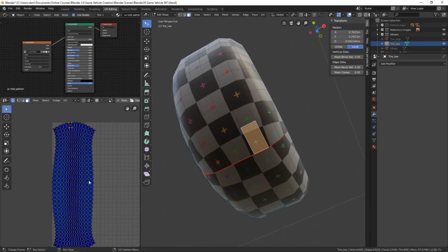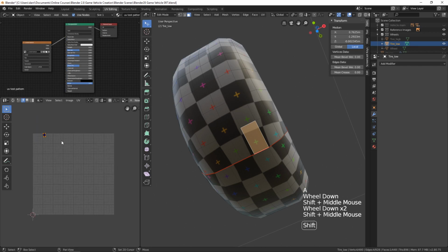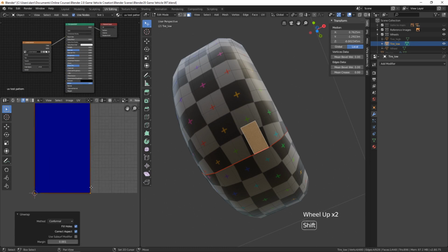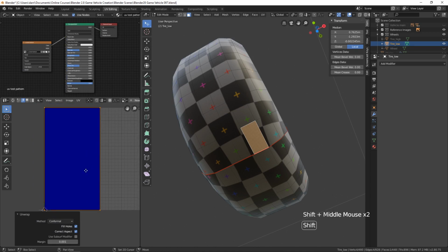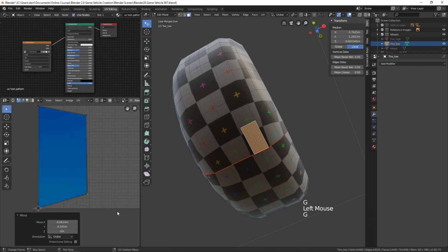What we need to do is figure out a way to get this quad to be more rectangular the way it is here in the 3D view. So what we can do is let's turn off UV Sync here. And here's that one quad, that one face. Let's hit the A key and let's just UV unwrap this here. In the UV editor with that selected, I'll just press U and there it is. Now that looks pretty good, right? That looks fairly rectangular.